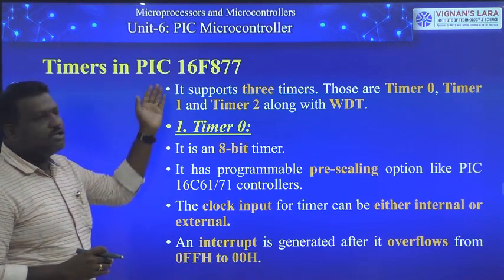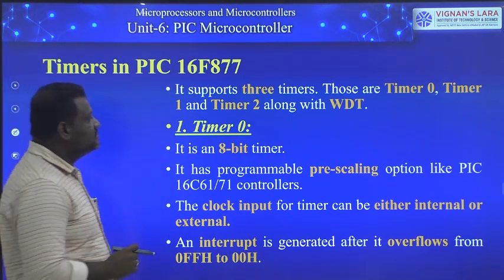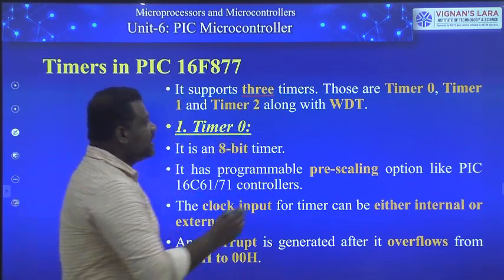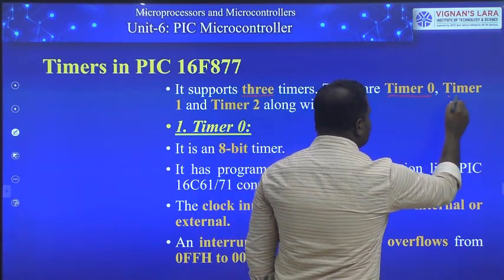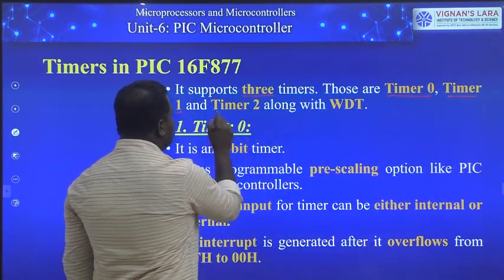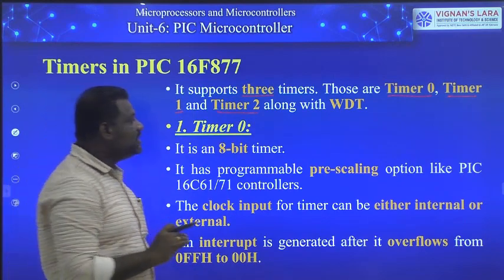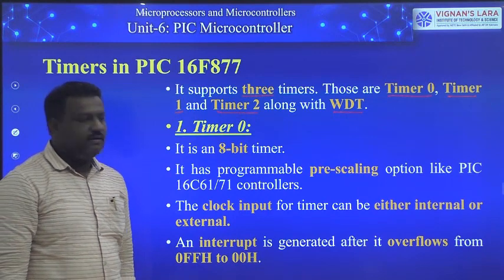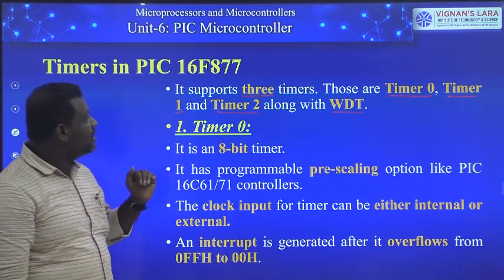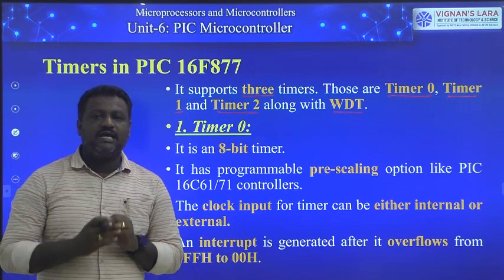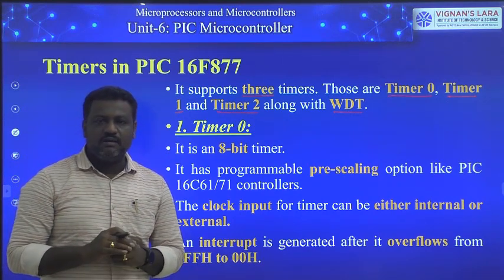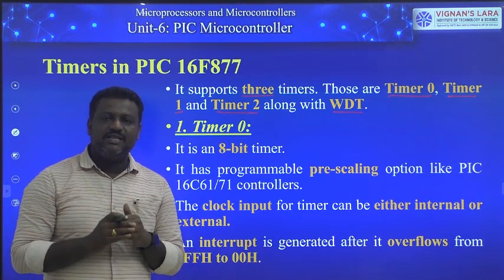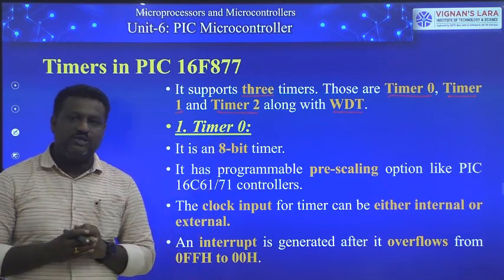In today's class, I am going to discuss the concept of timers in the PIC 16F877 microcontroller. This particular microcontroller has three timers: timer 0, timer 1 and timer 2, along with the watchdog timer, WDT. So I repeat my point: this microcontroller has three timer circuits, timer 0, timer 1, timer 2, along with the watchdog timer.